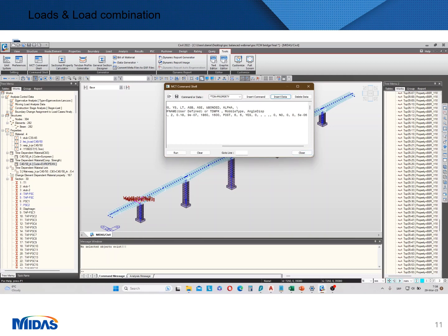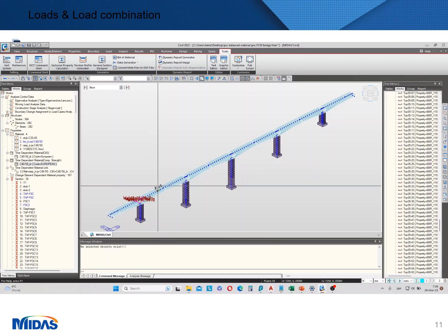You always have to be very cautious when you import or export these elements, so that you're always aware of which units you're using currently and which units are set in the model that you are importing to.